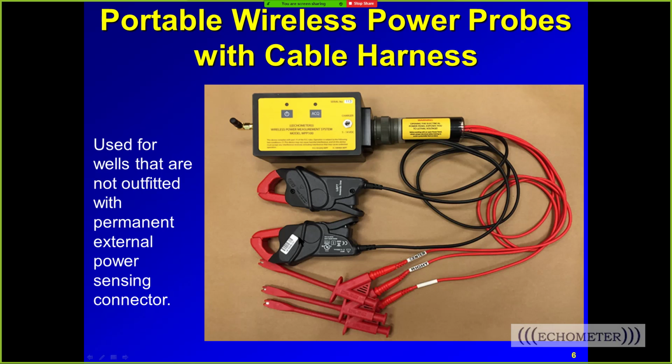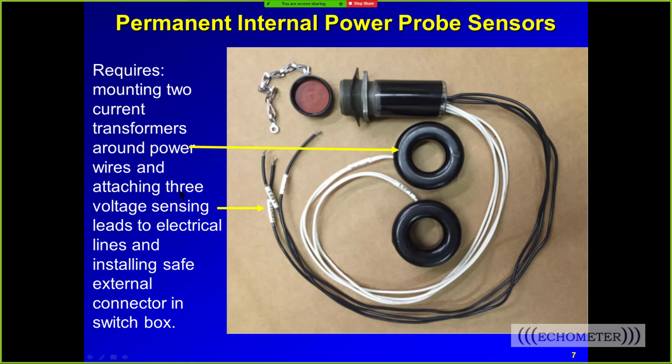And these are your two current sensors, and then this device outputs for the wireless system, as you acquire dynamometer data, the amps and the kW and the volts. And so you get an extra signal, the voltage, that we could then use to calculate the line losses. So we'll talk about this a little bit more, and a lot more in the last half of the presentation.